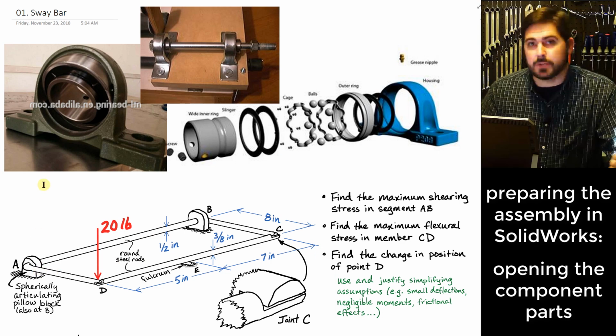These are going to take the places of those pillow blocks. I didn't really mention them just now, but at A and at B we have these special kind of bearings that allow angular movement in any direction. To simulate that in this SolidWorks technique, I'm going to use these little bushings that I modeled to be part of the system.